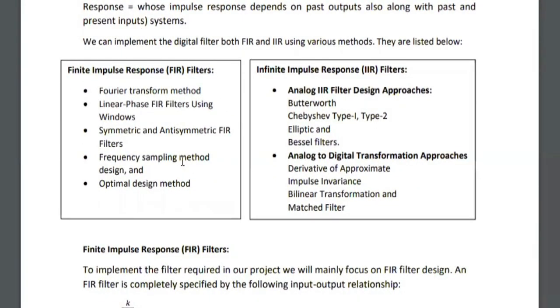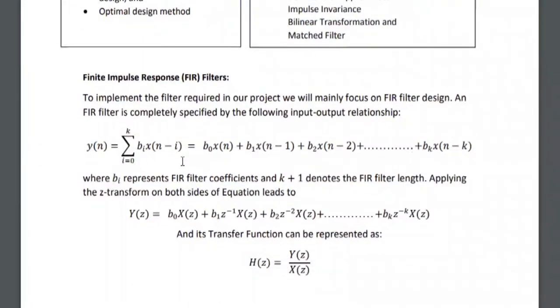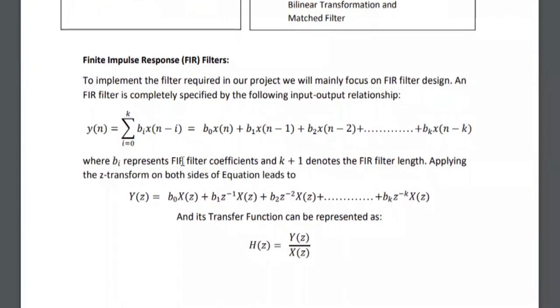We will use only a linear phase FIR filter using windows in our project. Finite impulse response FIR filters. To implement the filter required in our project, we will mainly focus on FIR filter design. An FIR filter is completely specified by the following input-output relationship. Here, all the terms are shown.